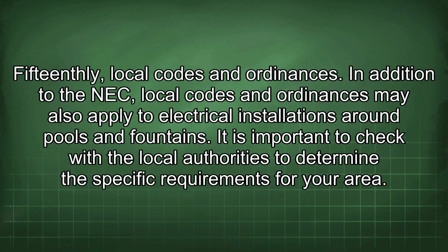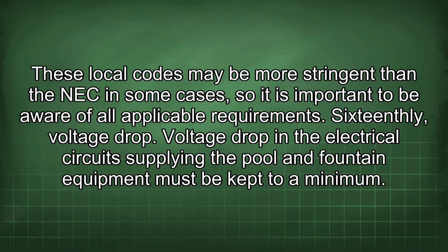15thly, local codes and ordinances. In addition to the NEC, local codes and ordinances may also apply to electrical installations around pools and fountains. It is important to check with the local authorities to determine the specific requirements for your area. These local codes may be more stringent than the NEC in some cases, so it is important to be aware of all applicable requirements.